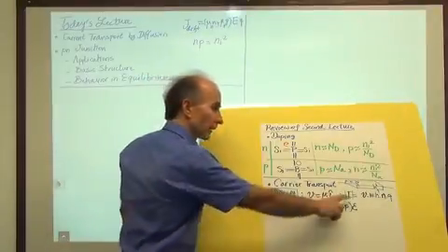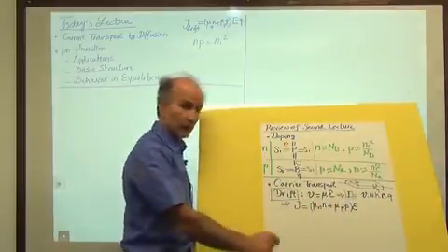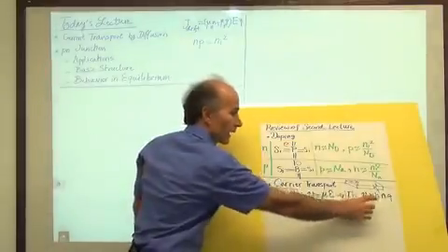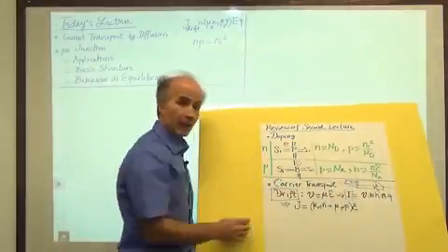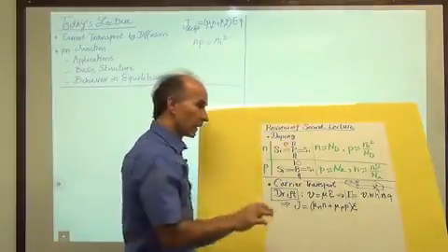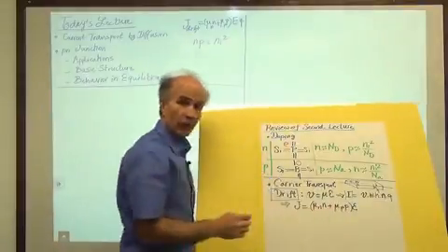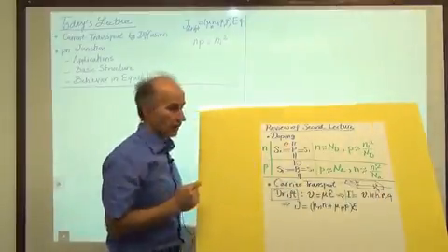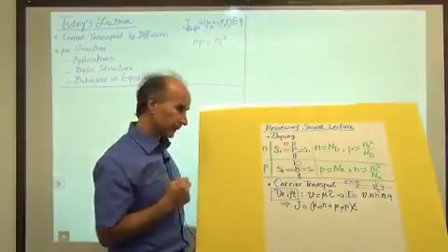So we derived an equation for the total current that flows, which was given by the velocity of the carriers, times WH, which is the cross-section area of the object we're going through, times the density of electrons or holes, times the charge on one electron to give us the total current.